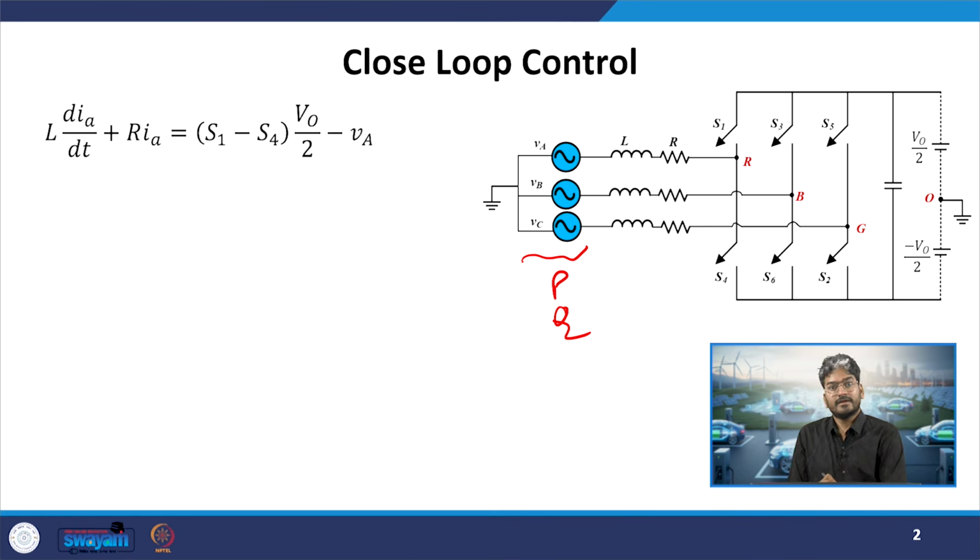Whereas we had three variables, that is our three phase currents which will be drawn or exchanged by the converter. So to avoid having three variables to control two parameters, we went through our alpha beta and DQ frame. Alpha beta was our stationary reference frame where we got two quadrature sinusoidal components, but the PI performance was better when we give DC signals to it.